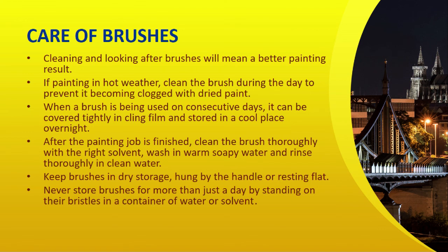How to take care of brushes. First is to clean and look after brushes for a better painting result. If painting in hot weather, clean the brush during the day to prevent it becoming clogged with dried paint. When a brush is being used on consecutive days, it can be covered tightly in cling film and stored in a cool place overnight. After the painting job is finished, clean the brush thoroughly with the right solvent. Wash in warm soapy water and rinse thoroughly in clean water.